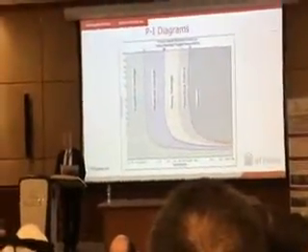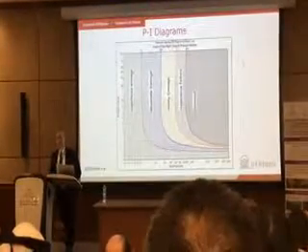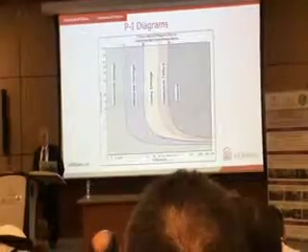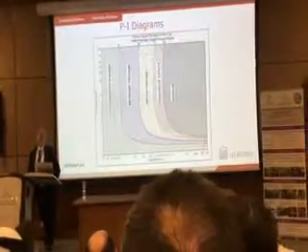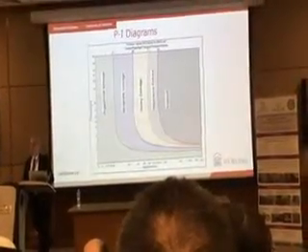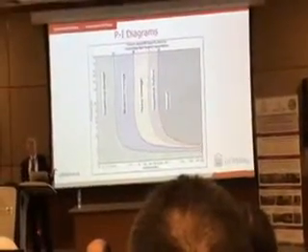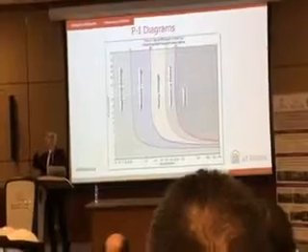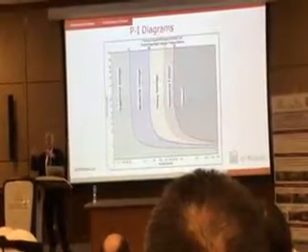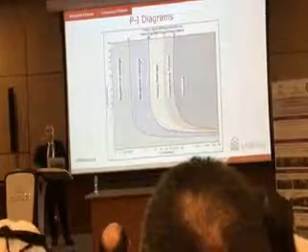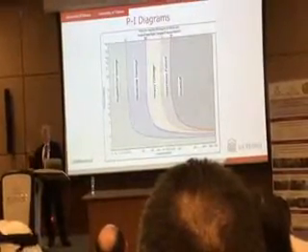Once again, my PhD student developed RC Blast, which is a freeware, and it's quite extensively used to develop PI diagrams. But just like column interaction diagrams, you need to have pages and pages of PI diagrams. If you don't want to do any calculation, just enter with pressure and impulse. Impulse is the area under the curve. Wherever the intersection falls, the performance level is accordingly.